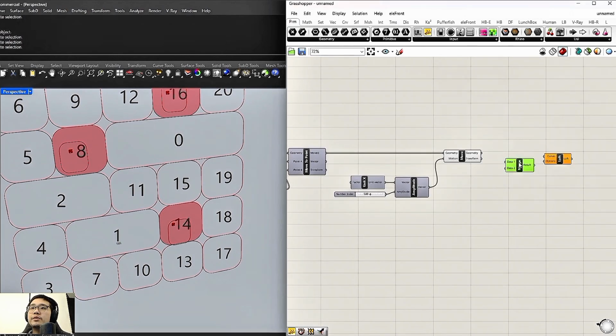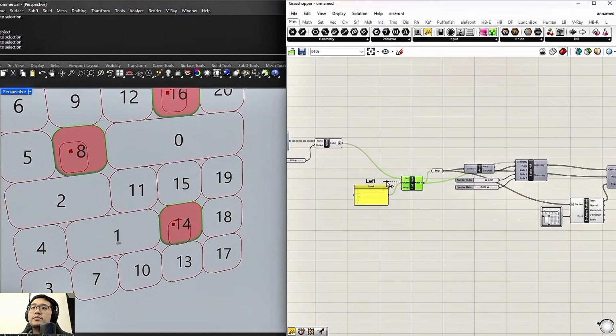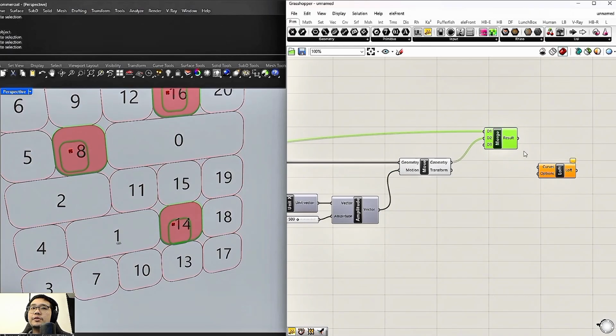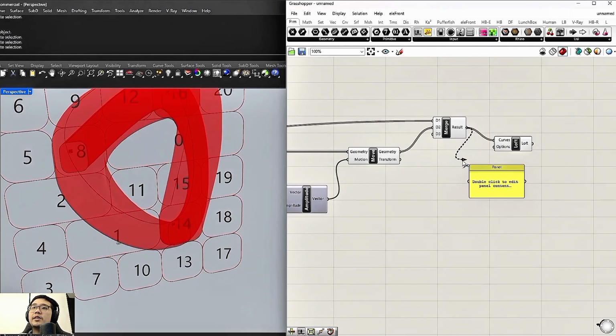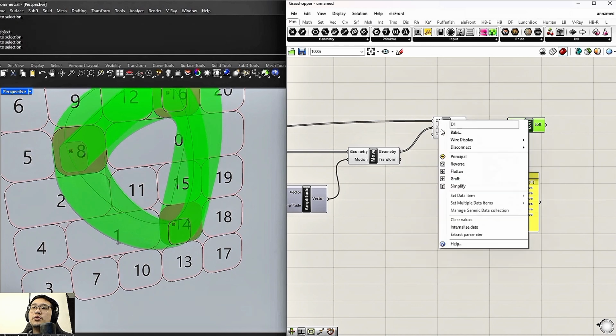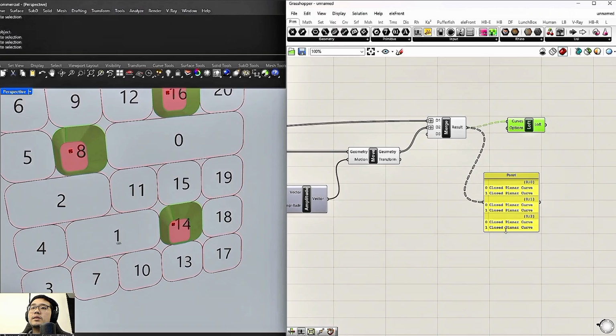I have to merge it down. So I have to merge fillet curve and this one here, so I can merge it together to generate a surface. But currently you can see, because it's merging together, it's actually trying to loft all 6 surfaces here. So what we need to do is graft this individually so that 2 surfaces can sit together in a list.